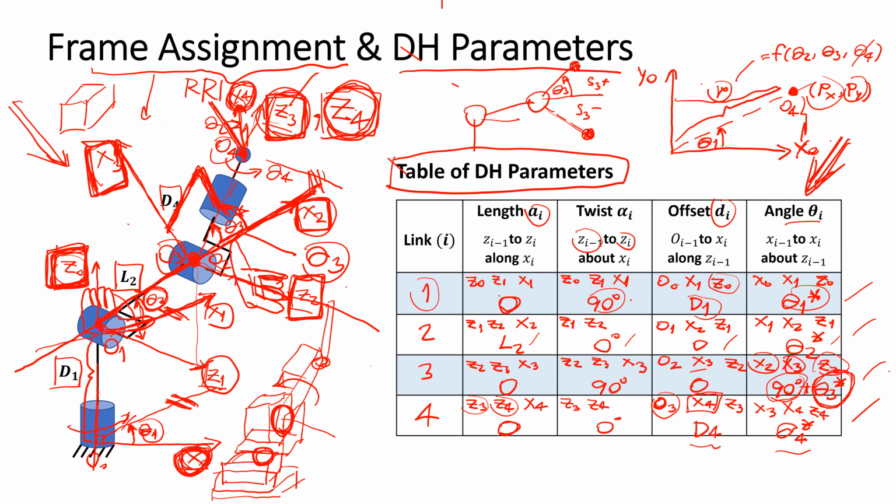If your robot need to reach something above this position, this offset D1, you may likely to have the sine to be positive. Or if it need to reach something lower, you need to use the negative case. But yeah, the endpoint position is important. The design orientation is also important.